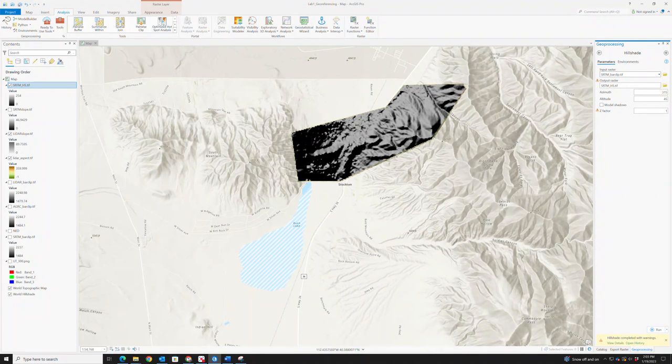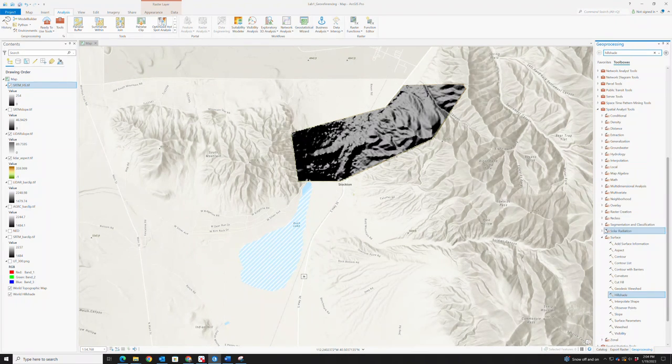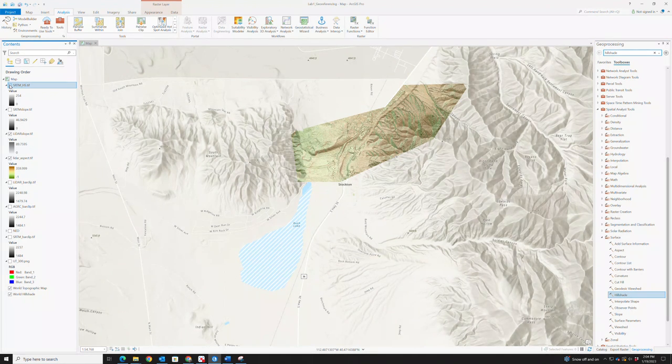And so then to solve that, you could do one of two things. You could either convert your coordinate system to a UTM projected coordinate system, so your horizontal units would then be meters, just like your vertical units. That would require no Z factor. Or you could go to a table and look up the Z factor to apply to a geographic coordinate system at the latitude that you're at. And that will make it look okay for the hillshade. So please do that. I believe you can just Google search that.